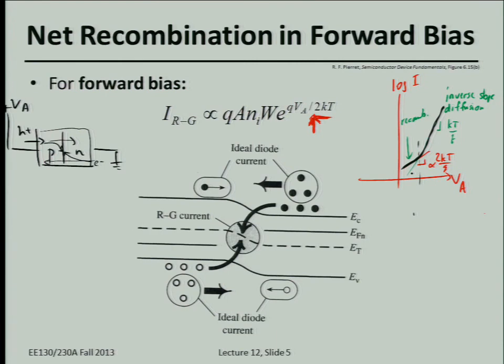As I mentioned before, usually when you form a p-n junction diode, in reality, we normally start with a p-type semiconductor. Then we blast n-type dopants, like arsenic or phosphorus, into the surface. So there might be arsenic ions implanted there. Then we have to heat it up at high temperature to heal that crystalline damage so that atoms can actually rearrange and form covalent bonds so the arsenic can sit on lattice sites to become donors.